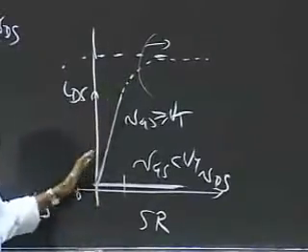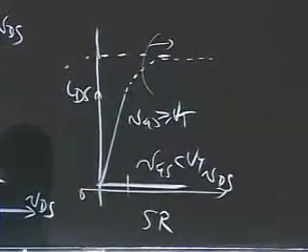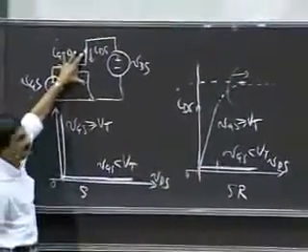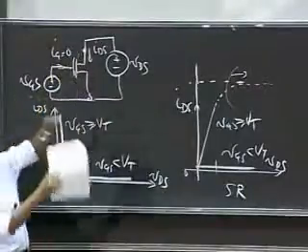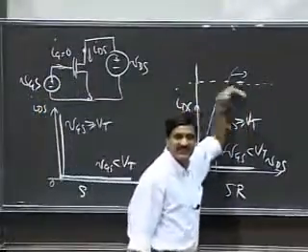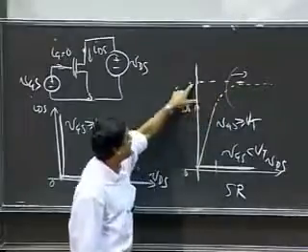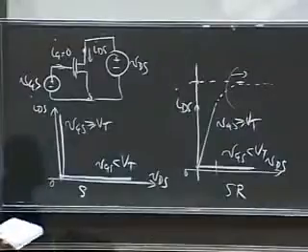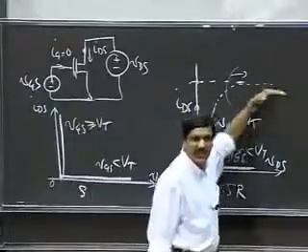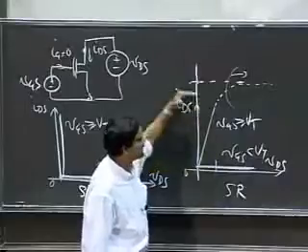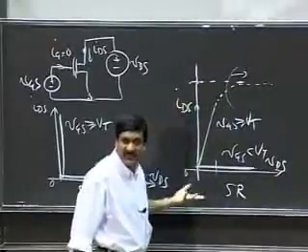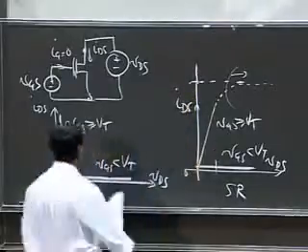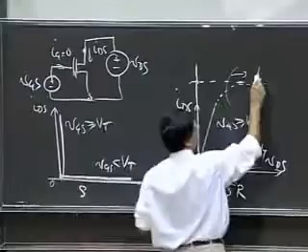Oh, it kind of looks resistive. But when I pump up the VDS, really whack this node hard with a much larger VDS, the device says, oh, I give up. The current saturates out, flattens out, and holds steady at some value. Okay, so what does that behavior look like? What's a horizontal line above the x-axis in terms of VI elements? What's that behavior like? Current source, exactly. So this is current source-like behavior.